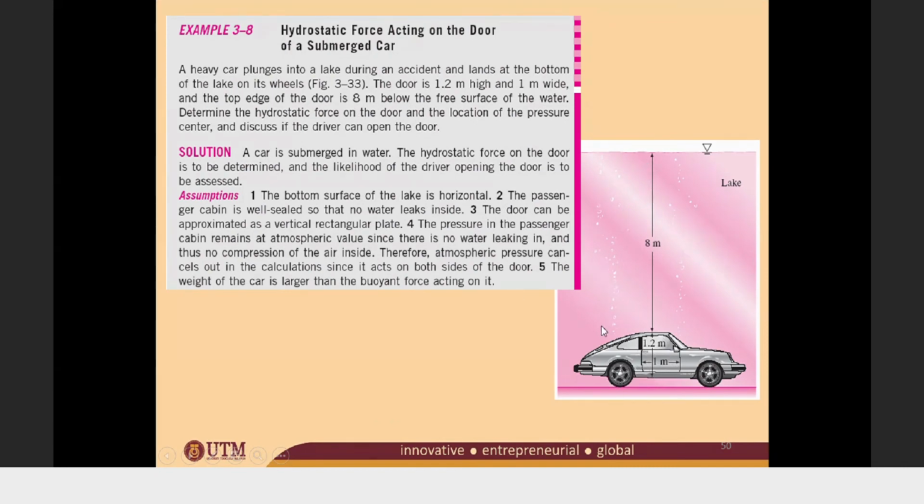Determine the hydrostatic force on the door and the location of the pressure center, and discuss if the driver can open the door.